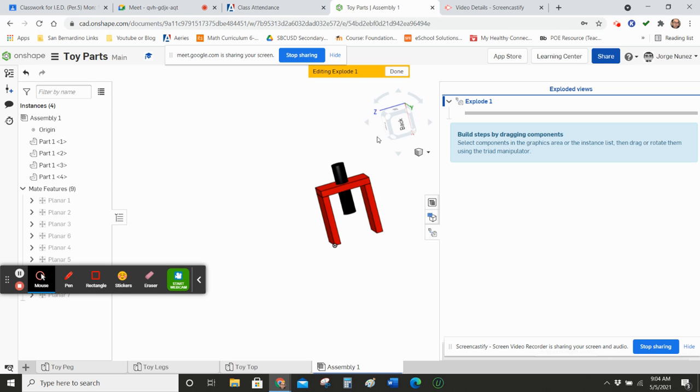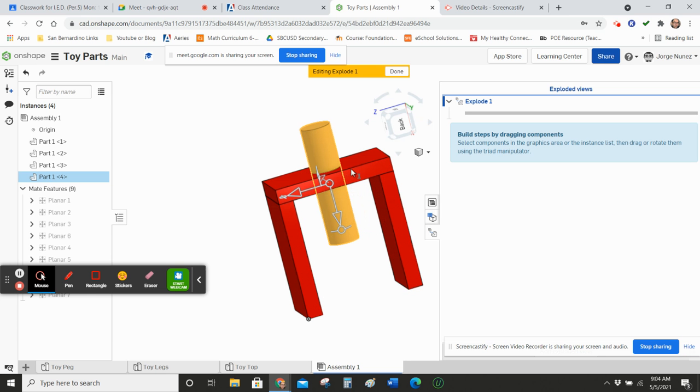So what we do here is we click on a part, let's say, for example, the cylinder. Then it allows me to move that part around or rotate it however I would like. They have different axes right now. Once I clicked the cylinder, I pulled up the X, the Y, and the Z axis, sometimes known as the Zed axis if you're in Europe. If you click on any of them and slide it in a direction, oops, sorry, you have to click on the arrow, by the way.